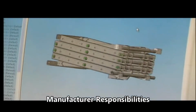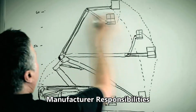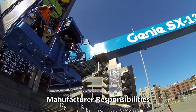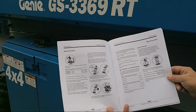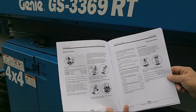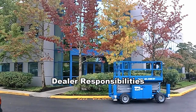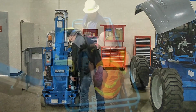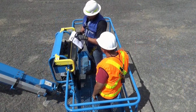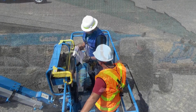To begin, manufacturers are responsible for designing equipment that meets these recognized standards. The manufacturer also has responsibility to provide operational and maintenance instructions and to identify potential hazards associated with operating or repairing the machine. The dealer, who may rent or sell Mewps, should make sure that the machines they provide are properly maintained and ready for use. The dealer is also responsible for offering appropriate training and familiarization regarding proper machine operation and safety.